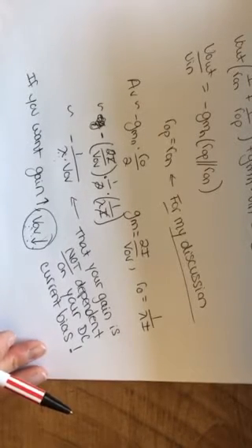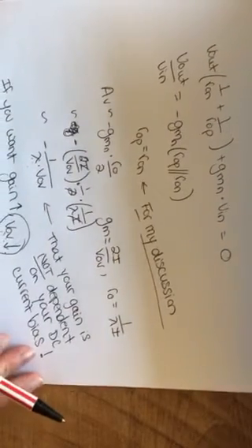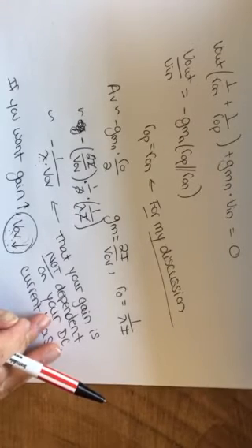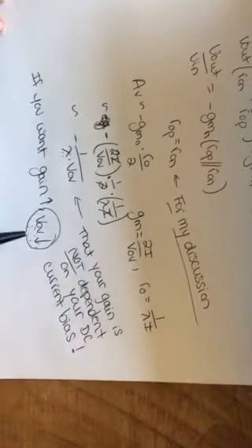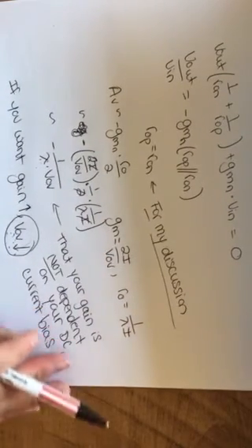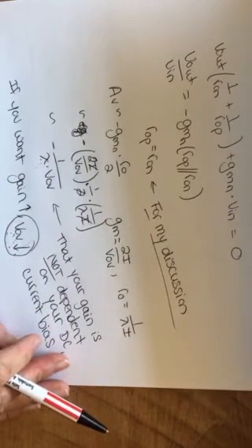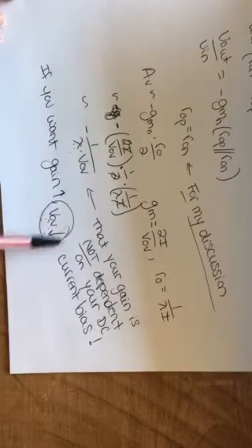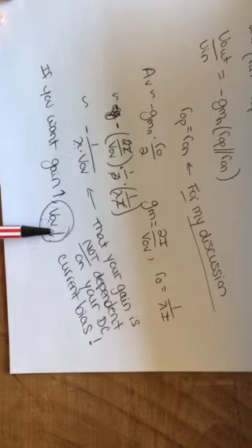Okay, so if you get to your lab and you realize you don't have enough voltage gain in simulation, you do your hand analysis, you derive your voltage gain, and you see I don't have enough voltage gain, going back and increasing the current through the circuit is not the way to get more gain. Instead, go back and reanalyze your gate to source voltages for your PMOS and NMOS devices and make sure that you are fulfilling your overdrive voltage criteria.